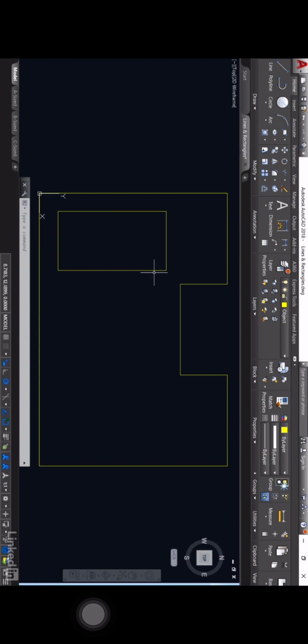Let's go back now to the rectangle command. Now I could go up to the draw panel, click on the flyout to get rectangle. I've just drawn a rectangle. I can press enter or spacebar to repeat the rectangle command. You can see it on the command line there. So I need to specify another corner point. This time it's going to be 18,4. There's the coordinates. Enter to confirm. And it appears over here on the right hand side.